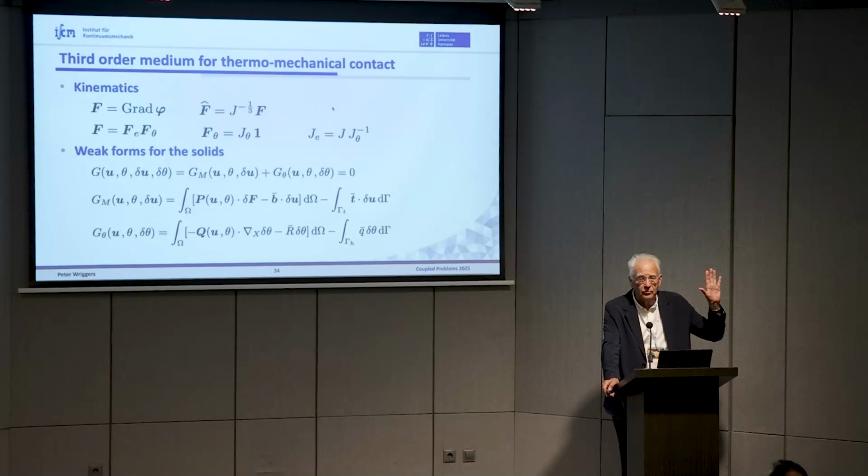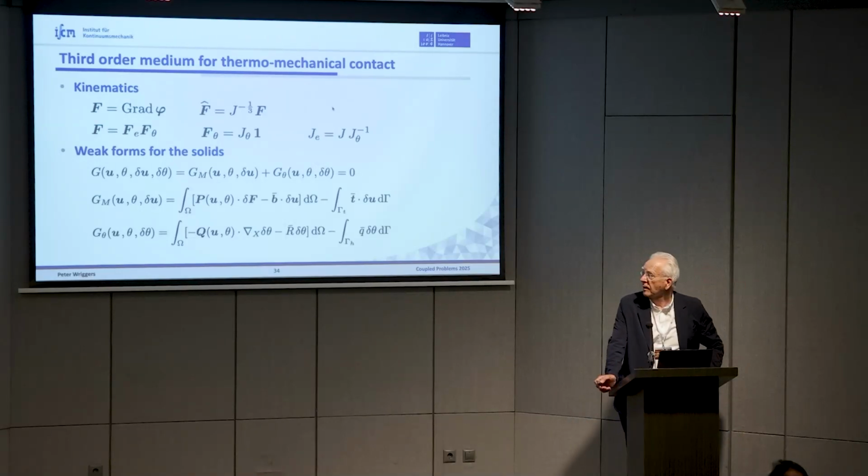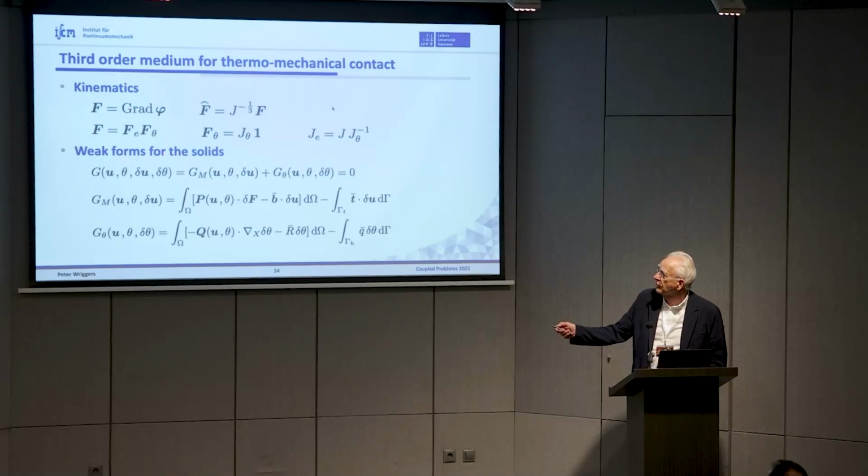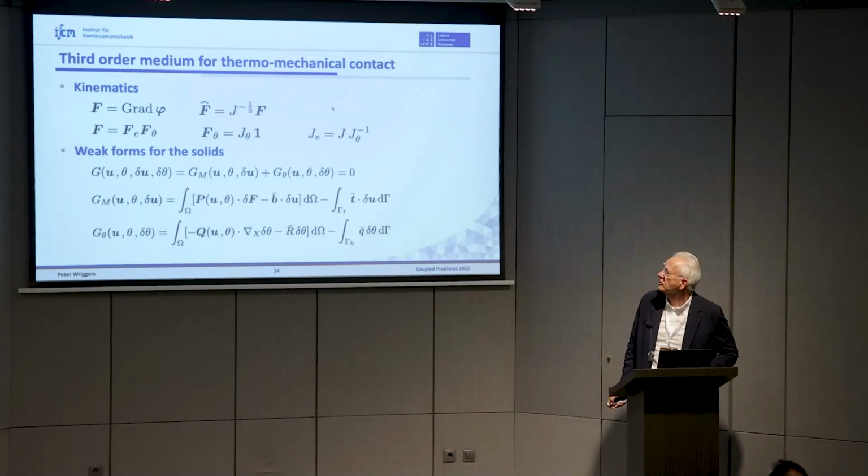Okay, so from this point of view, this was only deformation and deflection. Now what we want to do is thermomechanical contact. So we have to add the thermal part. First of all, you split the deformation gradient into an elastic part and a thermal part. The thermal part classically is only governed by the volumetric change related to the temperature.